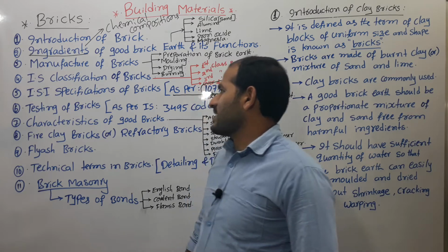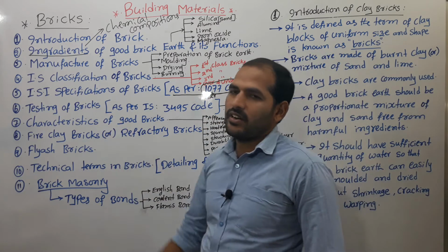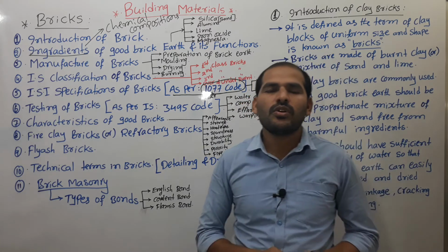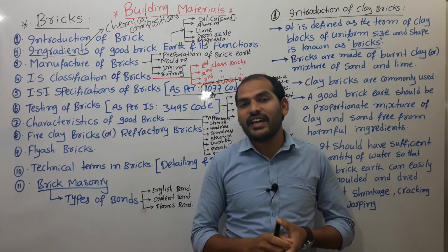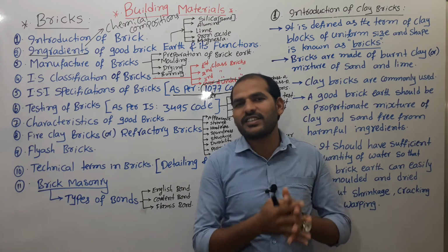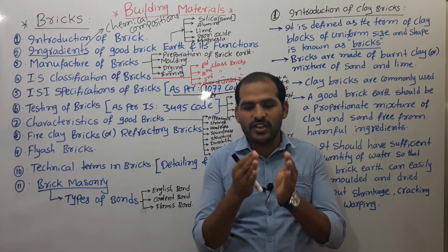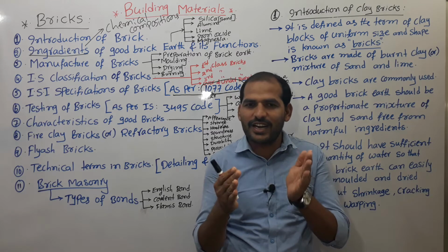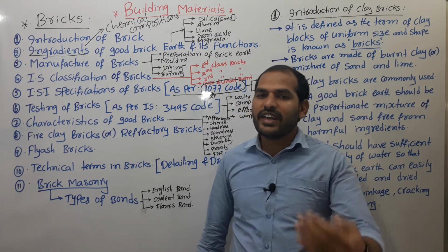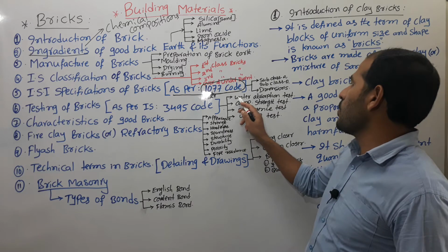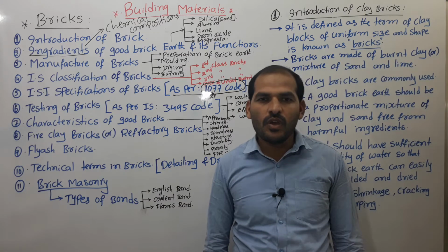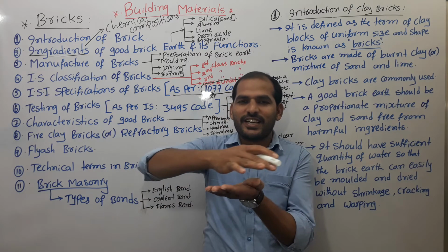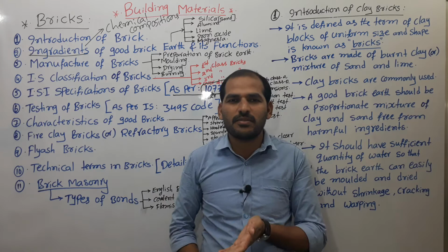And the next one is testing of bricks. Testing of bricks means which tests are conducted on the bricks for deciding whether the brick is a good brick or is not to be used for construction. The brick classification, that is first class brick, second class brick, third class brick, is based on the tests. The different tests: first, the water absorption test.